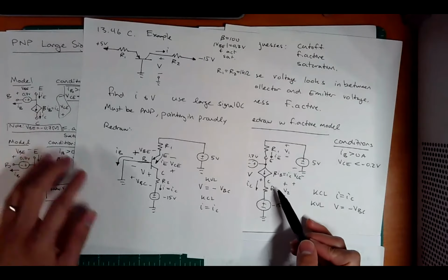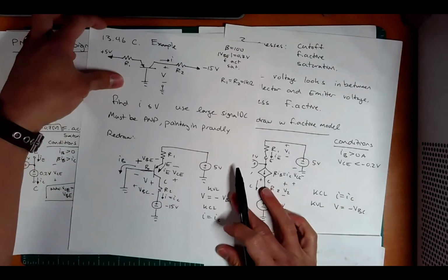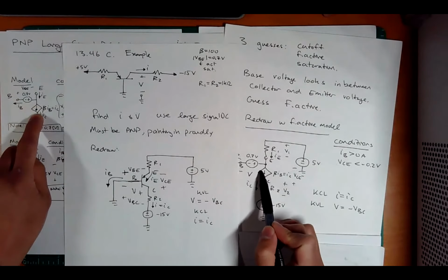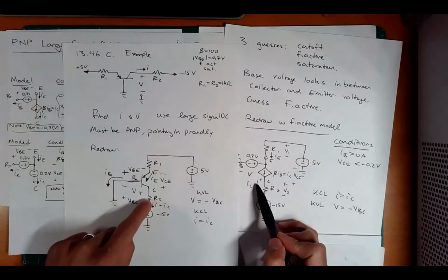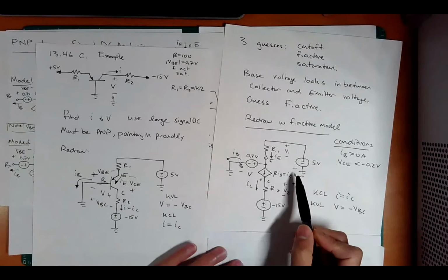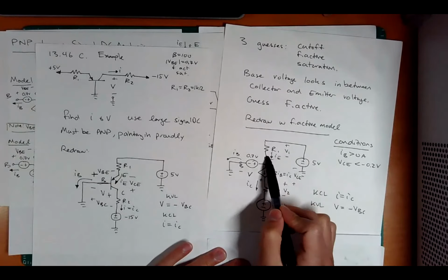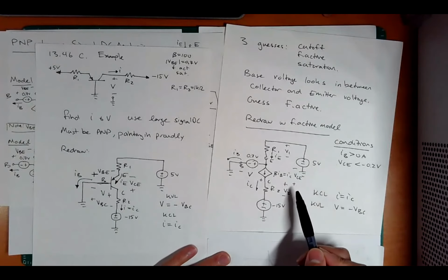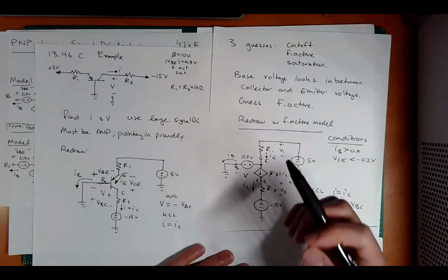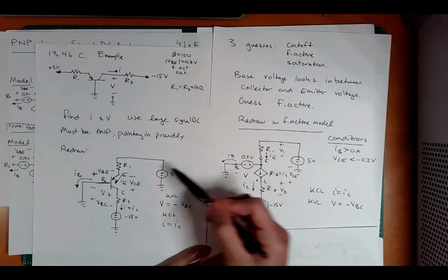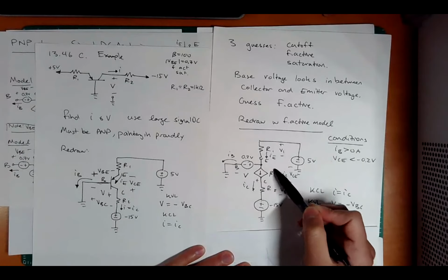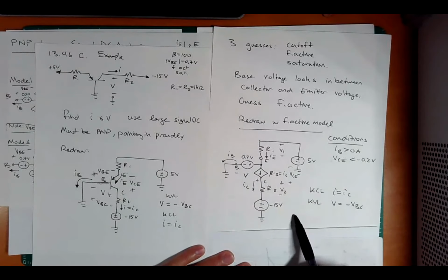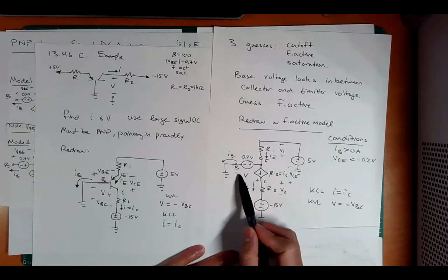And so I would, okay, that's a little tricky, but I just got to be careful. It's not too bad. I put in that 0.7 volt, I orient it correctly, and I put in this current controlled current source, but otherwise everything around it is the same. Okay. Now notice I put a voltage polarity over here across the R1 and the R2. Okay, so I know it looks pretty complicated, but if you stick to your ET250 fundamentals, you should be good. Notice I have VCE across the current controlled current source, IC drawn, -15, so everything is consistent. Still KCL, I equals IC, still KVL, V equals -VBC.